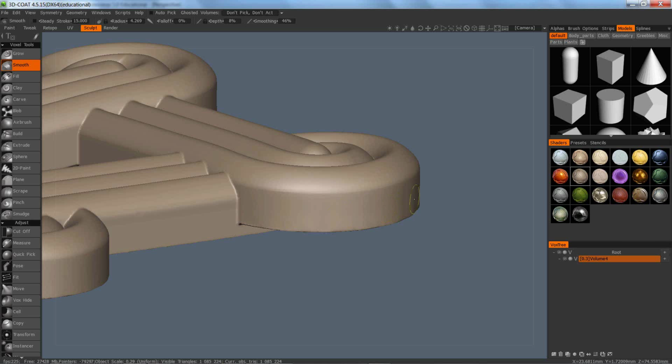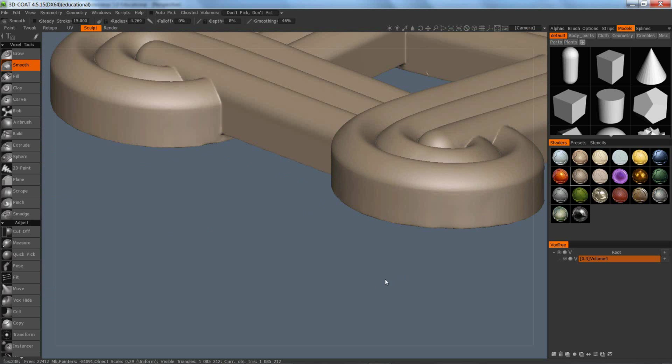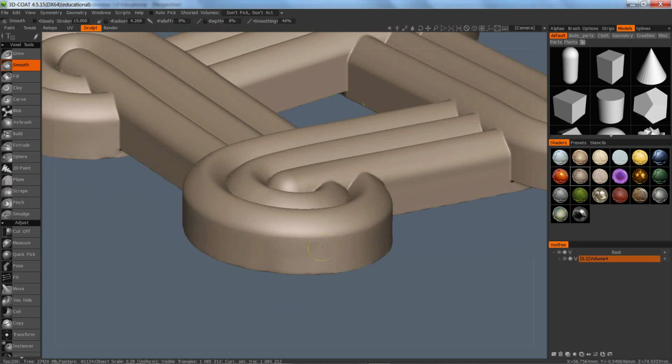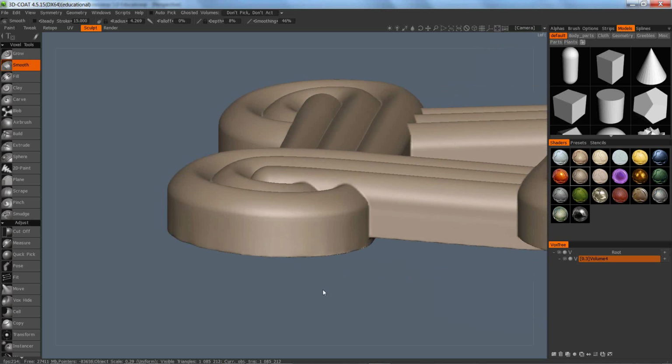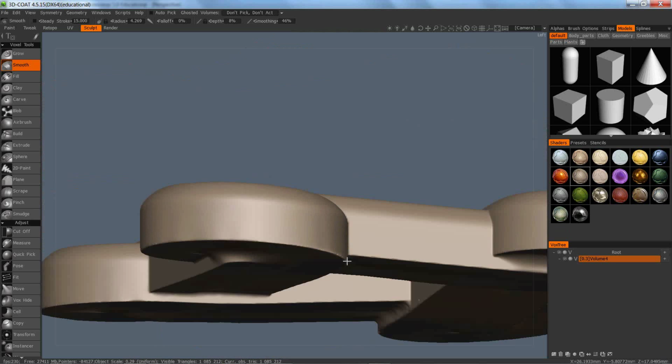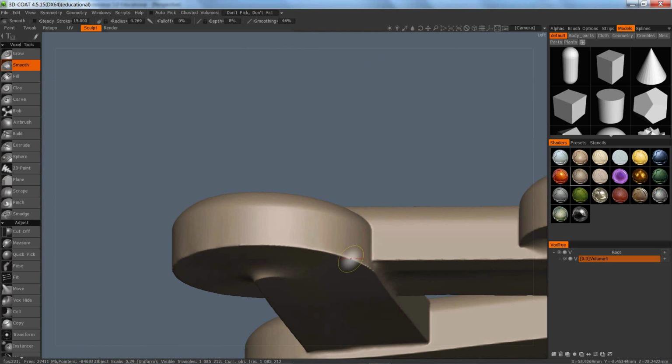Rhino has what they call an optimized mesh, where it puts a great big loose mesh where there isn't much detail, and fussy tight mesh where there's lots of detail. That's really bad for a sculpting program, which basically wants a consistent density of mesh everywhere. It's triangles, whereas sculpting mesh is like quadrangles. So what you're seeing on those things is a texture of triangles.